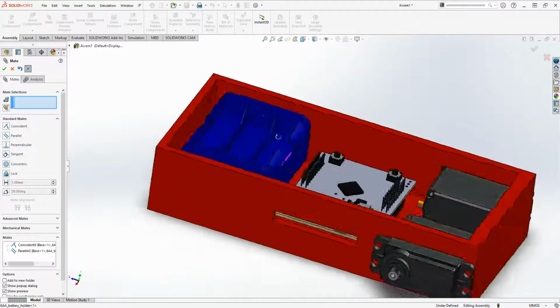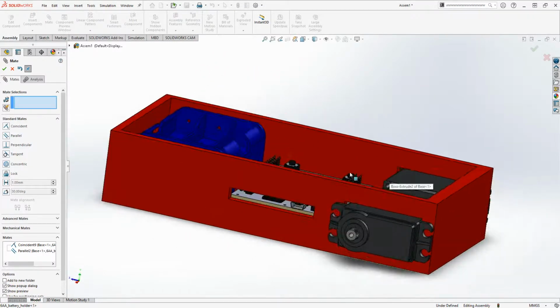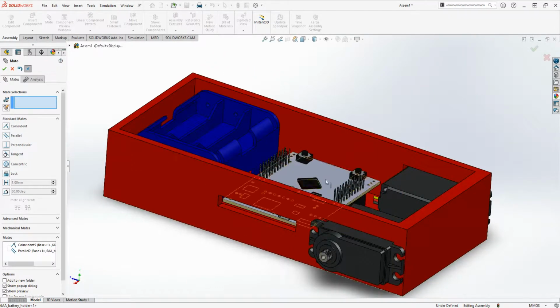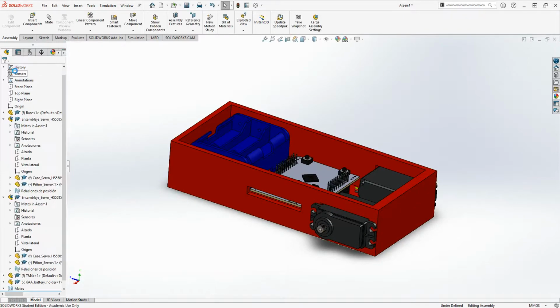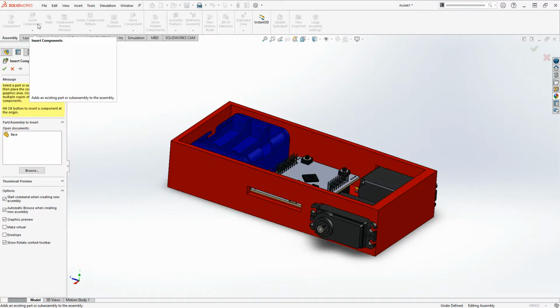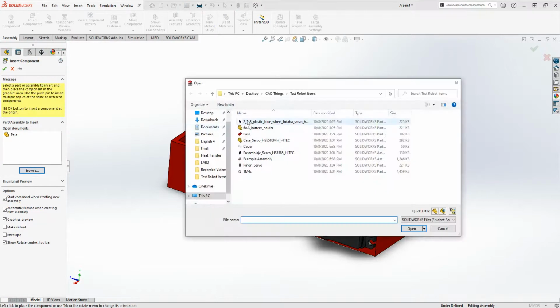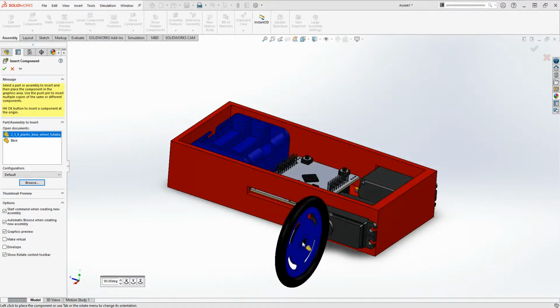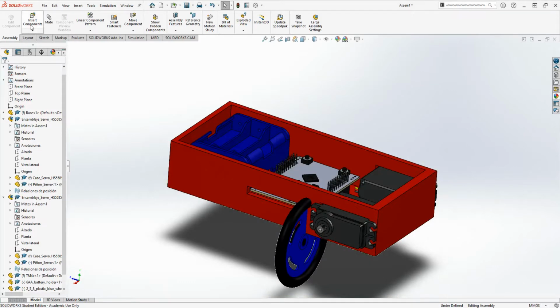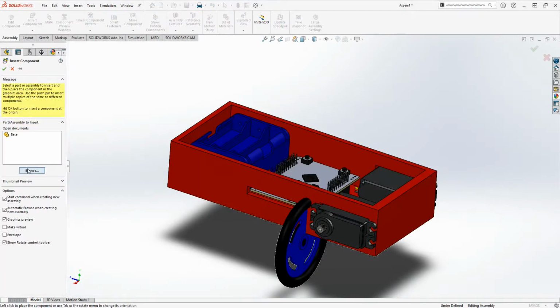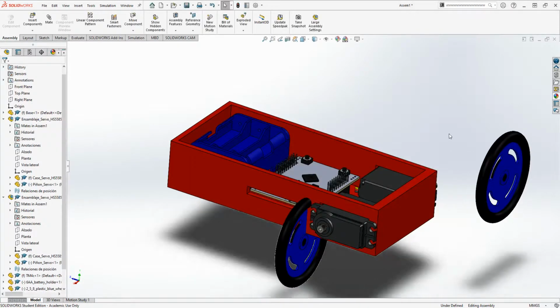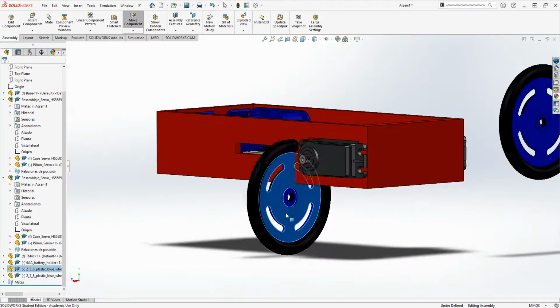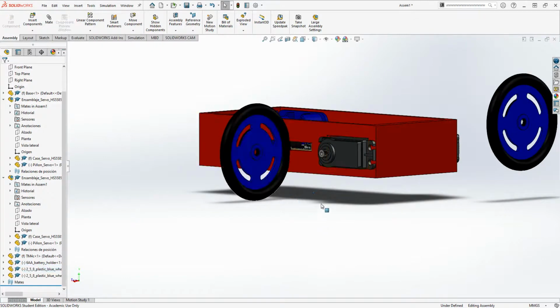So I'm going to zoom out and rotate this around, because as I've said before, it's always helpful to rotate your components the way you'd want to place them down in your assembly. There we go. Looks great. It's kind of in place there now. So let's start with a couple things. As we said before, let's mate. Always best to mate on the plane first. So I'm going to select a little plane here. Select the bottom plane. Great.